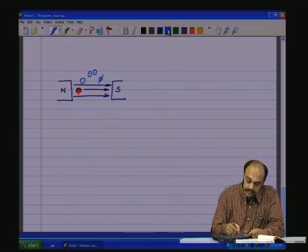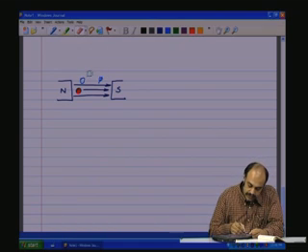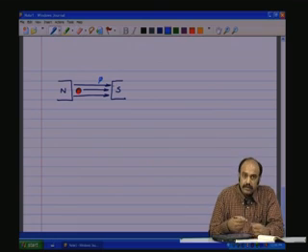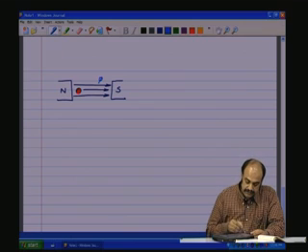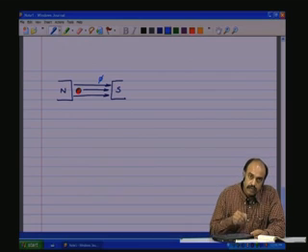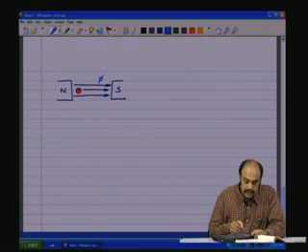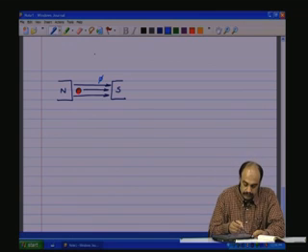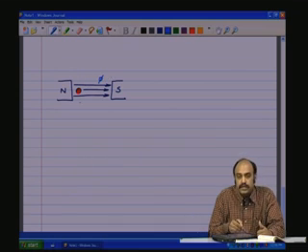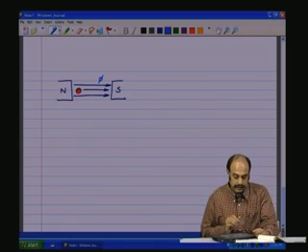So, in the case of DC machines, the flux here is kept constant by means of fixed permanent magnets, let us say, or something that produces constant flux, and thereby the only way that you can produce an induced EMF in this conductor is by moving the conductor along the periphery, which means that this conductor is going to see varying amplitudes of the flux at different points on the circumference of the circle, and therefore a d phi by dt, and therefore an induced EMF, and therefore a current to flow through the conductor.